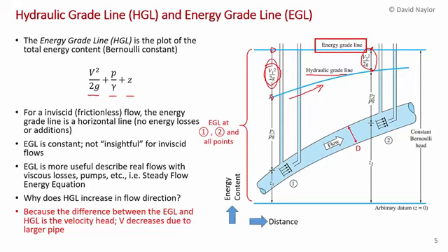And what's interesting is in this flow, you can see that the pipe diameter is gradually getting bigger in the flow direction. That means that the velocity is going to be decreasing. The average velocity will be decreasing because of continuity. So you'll have less kinetic energy in the flow as you move downstream, and so the hydraulic grade line will approach the energy grade line. Basically what's happening is you're converting kinetic energy into pressure energy. You're converting velocity head into pressure head as the flow moves downstream.